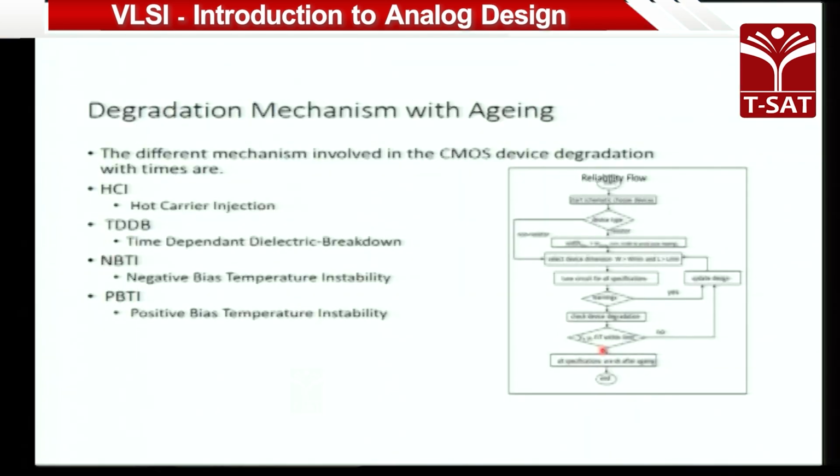Now what is a netlist? I think I should give you some understanding. A netlist is a kind of model, like you have small device models. You connect those models and then you form a bigger model of the entire circuit. That model is connected, one model to another model, in a form, and that form is nothing but the netlist. Now what the tool will give you is a fresh netlist and another is a stressed netlist. This stressed netlist is stressed over a period of 10 years. You don't have to wait for 10 years. The tool does it.